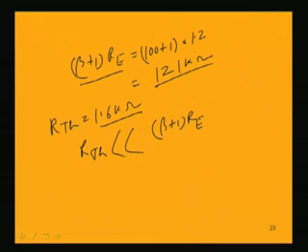That is why the potential divider biasing scheme, or voltage divider biasing scheme, is used very popularly in transistor amplifiers. Mostly this potential divider biasing scheme has advantages over the other biasing schemes already discussed, like the different variations of emitter bias, such as collector emitter feedback bias.